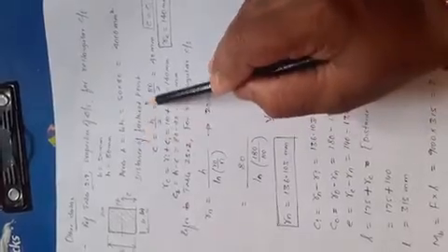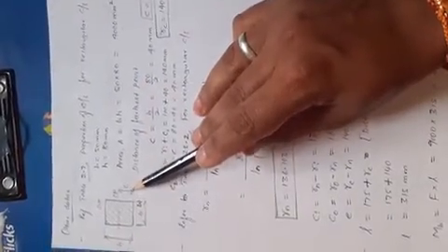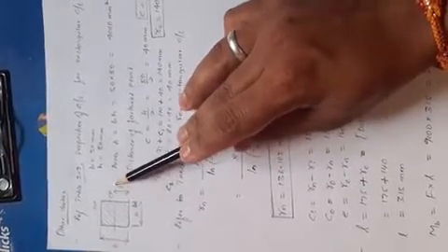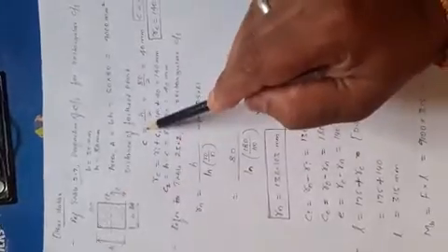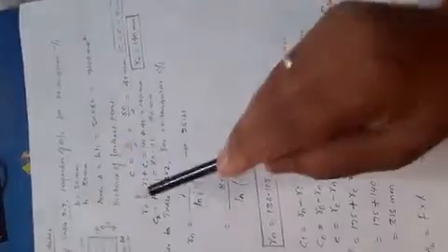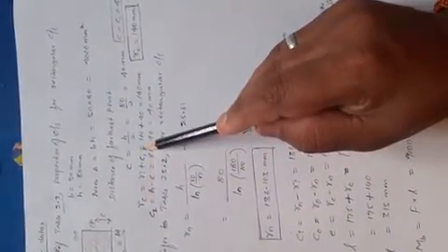Now the distance of the farthest point, C, is indicated in table 2.7 for the rectangular cross section. From the inner fiber to the centroidal axis, the distance C is equal to H by 2, that is 40. This is also equal to C1. Then as you know, Rc is calculated as Ri plus C1.